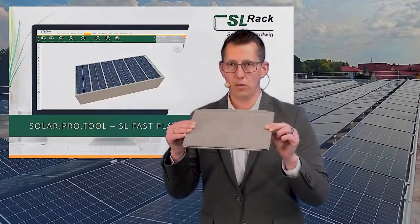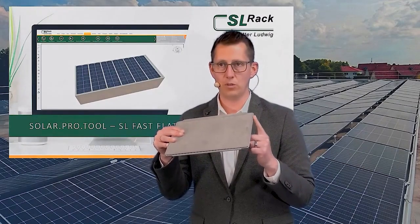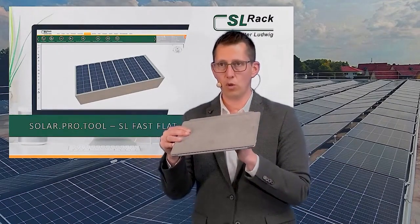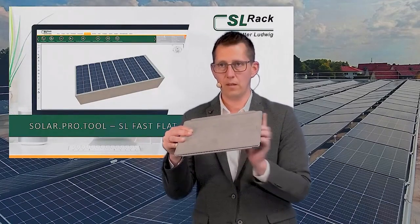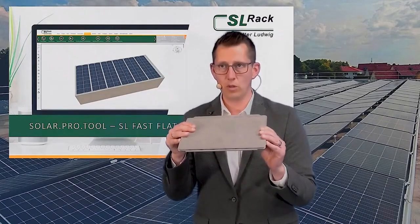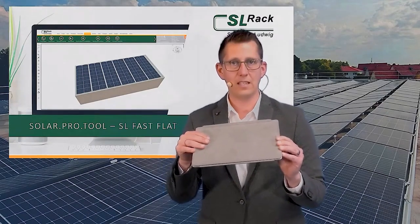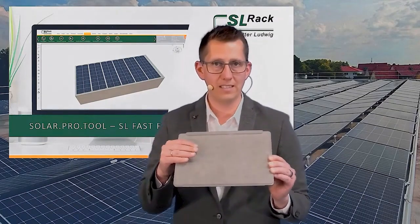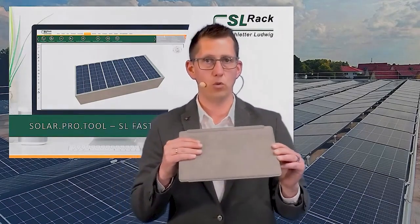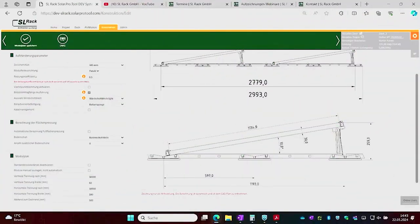Our PV module, symbolically shown. In the background, you can see corner clamps. The clamps are here. For those who want a quarter point clamping, the clamp is placed in the quarter point here. Very important, when a quarter point is built, a stiffening plate is added behind it. This will be explained in a timely manner in the assembly instructions, installation manual, and assembly video to be self-explanatory and understandable for you, but simply to explain what a quarter point clamping is and how it works.